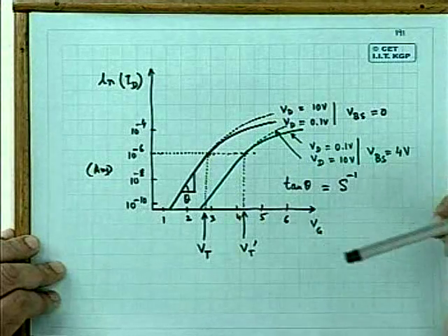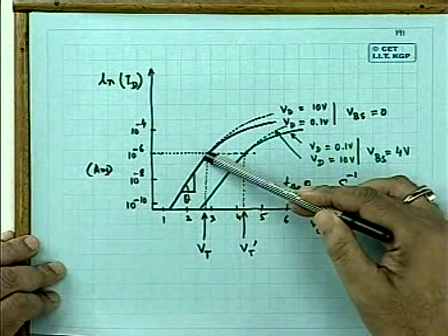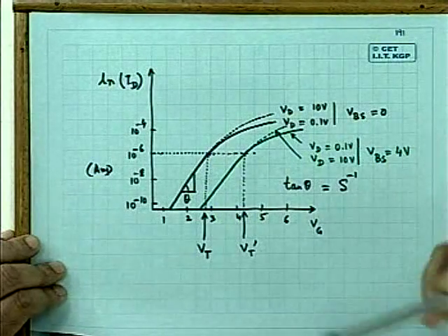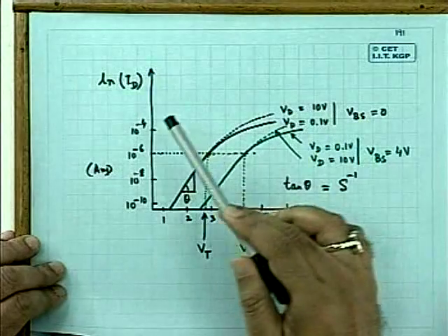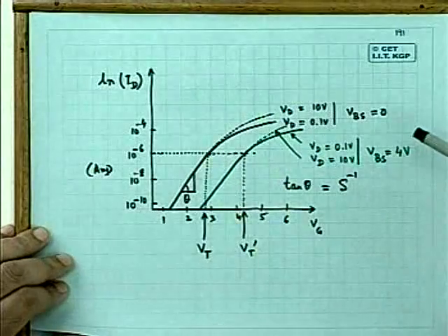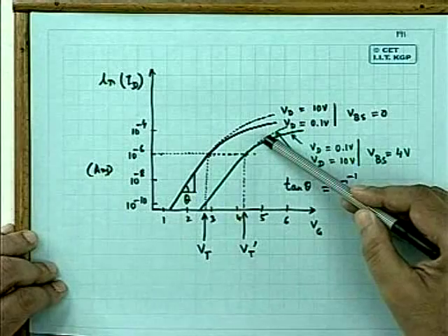In practice, when you make a device, and if you are interested in determining the value of the VTH, it is better to plot ID versus VG and see where the threshold is occurring. At which value of gate voltage suddenly the current rises from 0 to a certain value, called threshold. But actually, when you plot in the log scale, not a linear scale, it is a very sharp rise, but a logarithmic rise, that means exponential increase.